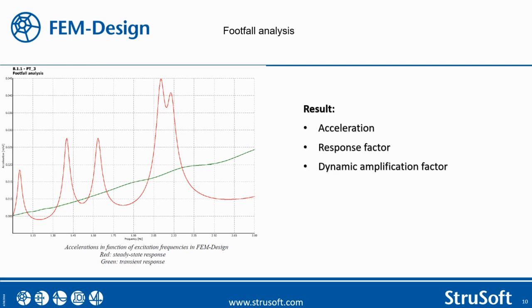This is very important, so I'm going to say it again: the peak values appear when the eigenfrequency of the structure is equal to the excitation frequency or its harmonic. This is called resonance. I will show you what I mean by that when we run some examples in FEM-Design.